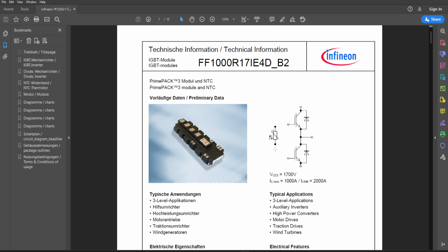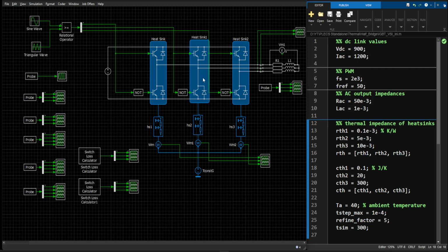But the example that I showed you was a half bridge, and that actually didn't convey a realistic meaning. That means we had considered a heat sink, but we connected it only to one device. But in practical situations, this is a little different. For instance, if we have a two-level, three-phase inverter like this, we'd have three different legs, as you can see here, 1, 2, and 3 for the 3 phases. And each half bridge would then be mounted on a heatsink, be it air-cooled or liquid-cooled.